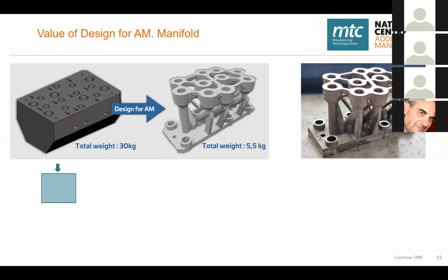So for example, in that one, if we make a very rough estimation, assuming that the component is 150 by 50, I don't know exactly the dimensions of that component, and we think about 0.1 millimeter layers, which is a very common layer thickness, and a beam diameter of the laser of 0.7 millimeters, that means that the laser, to create that component, needs to travel 3,500 kilometers.